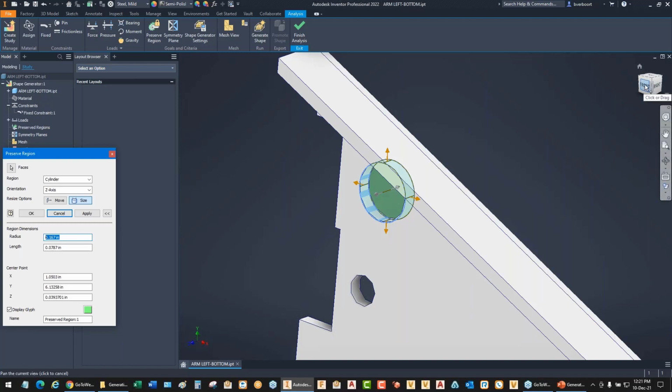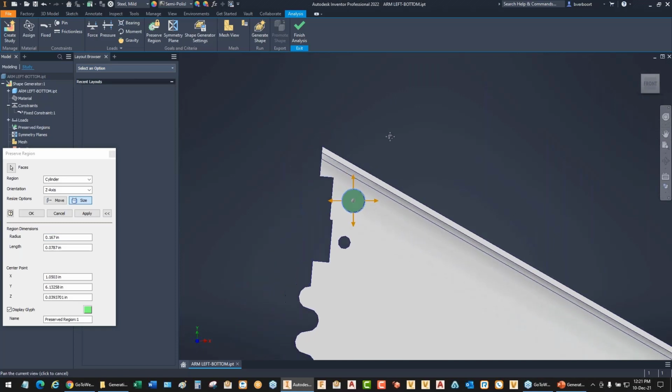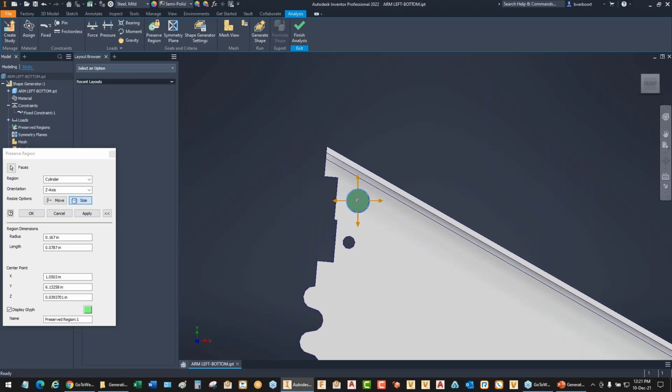Once I've selected it, you'll see, because what I picked was circular, it's created a cylindrical bounding object. And this thing's editable. We can make modifications to its size. You notice as I make these changes, just by dragging the glyphs, the manipulators in Canvas, that the values for the radius and diameter are updated.